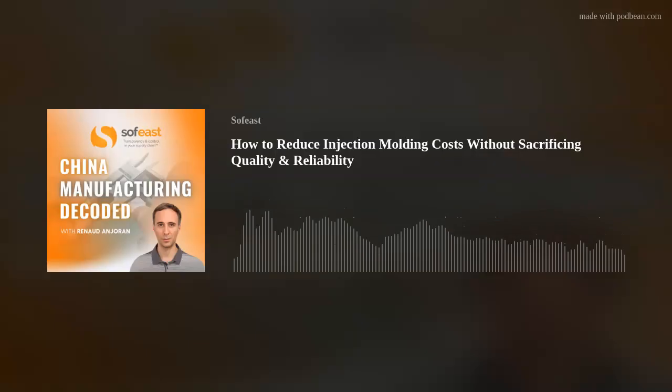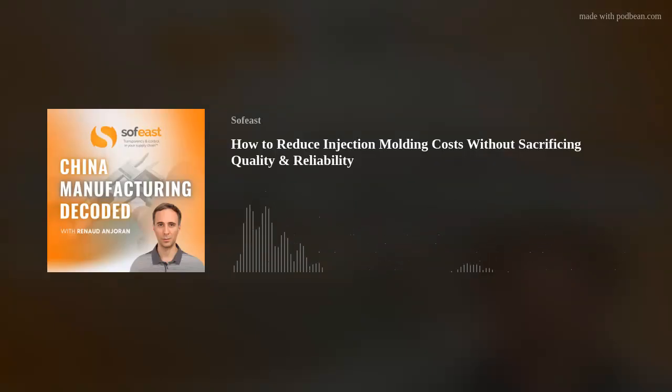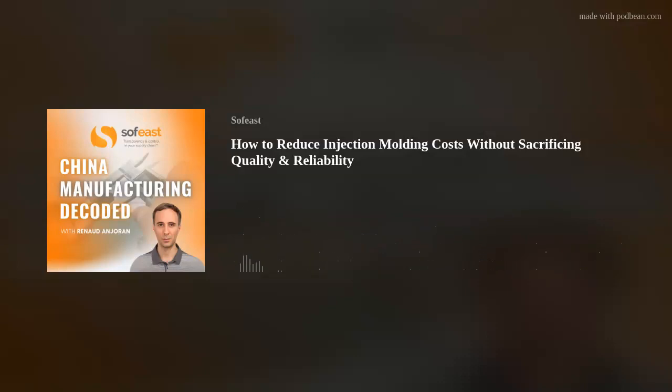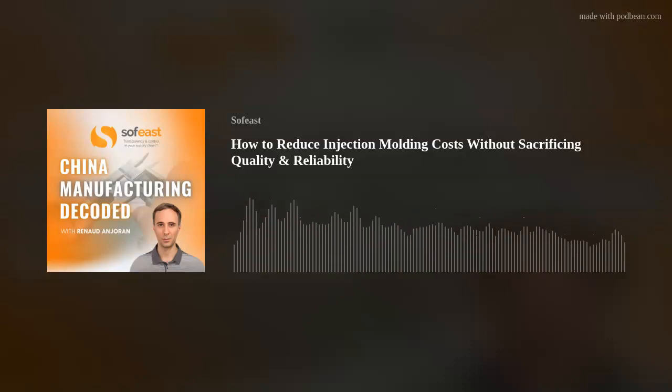And this is really down to the 2D or the technical drawing from a specification point of view on the tolerances. Okay, your toolmaker will follow instructions. All right, so they'll have the 3D CAD, and they will have the technical drawing, the details on the 2D drawing, which specify your tolerances. Now, if you go blindly in and saying I want 0.05 millimeters on absolutely everything, and you get a ridiculous tooling quote back, and you think, well, why is it so expensive?